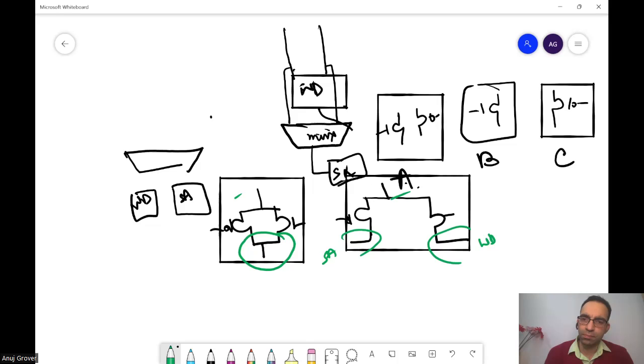Sir, if we use the second case over here, because the sense amplifier is after the mux, even small differential voltages can be sensed. So we can use a single NMOS for the sense amplifier, and if the write margin is really good, then we can use this for the word line as well, the write driver as well. So what is the benefit of the second configuration over the first configuration?